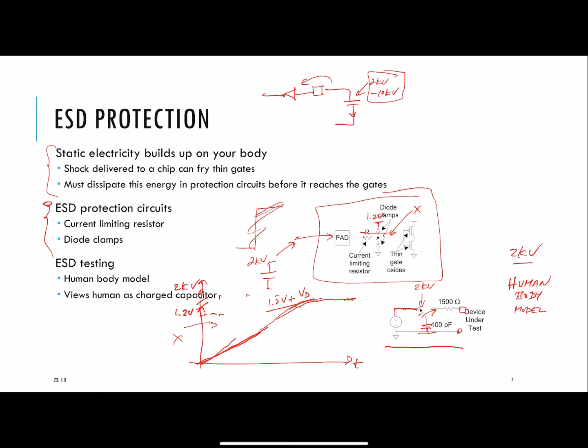So this ESD is, again, a very scary issue. We've had structures that fail ESD, and when ESD fails, it's really, really bad news, because you can't fix it with just a couple of mask layers. You really typically have to go change all your mask layers and try to fix it.